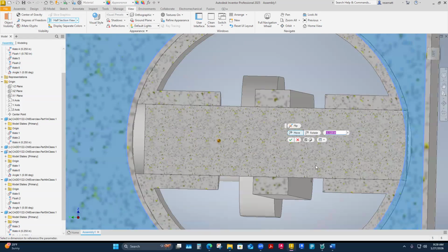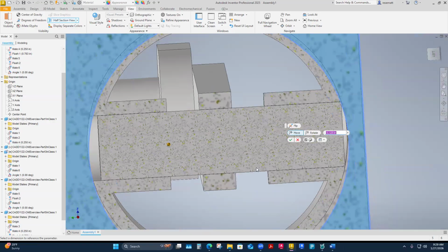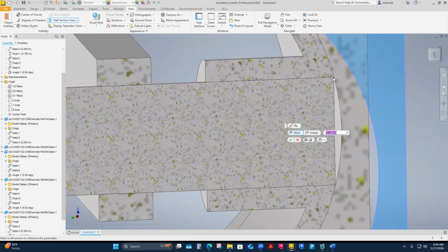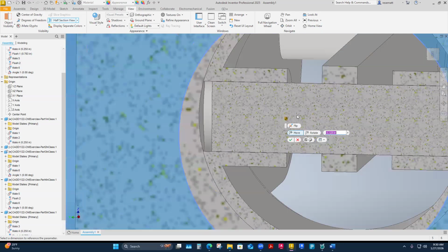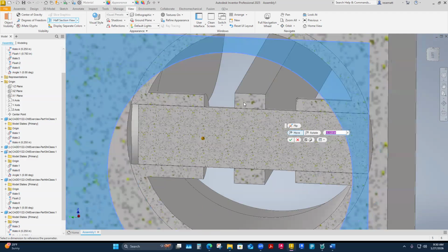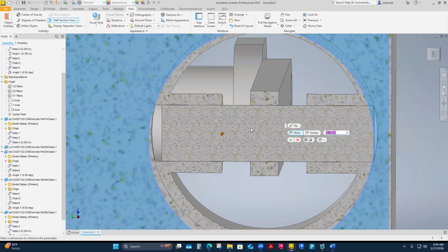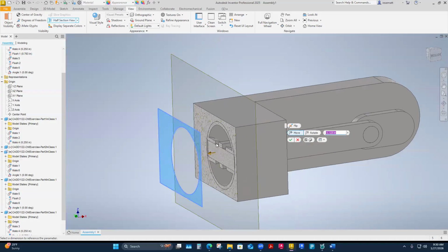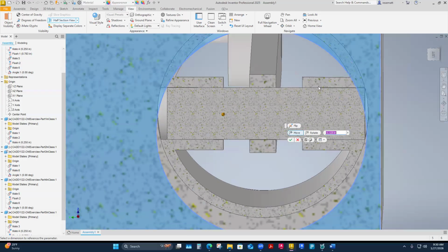I don't love the alignment here of that wrist pin. Maybe I'm using the dimension they gave me from an opposite face. I can tell here that the dimensions I've used for my wrist pin, while they look good, when I look at the section, I'm definitely not centered. It could be that I'm using the wrong face selection with that dimension. I don't know though; I'd have to troubleshoot my constraints a little to see if I've got that centered. Ideally, this part should be centered in the piston, in the little parts that hold it.